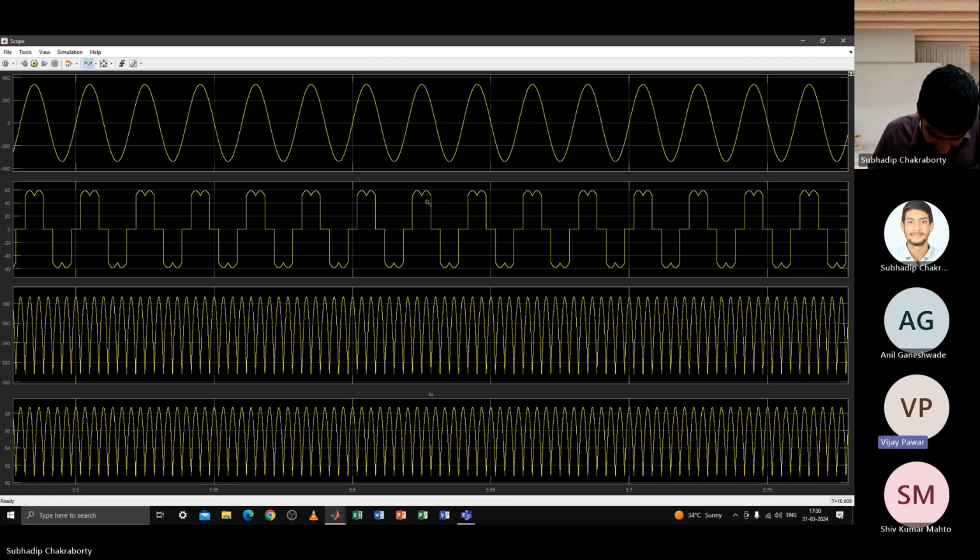Please understand, there are harmonics. So if you want to provide harmonic compensation, which you will do for these kinds of loads, such that your supply side doesn't have any harmonic, then the current rating of the filter will not be 0, because your filter will provide a low impedance path to the harmonic components. Then how can it be 0? Only the reactive component of your current is 0. That's why you don't need reactive power compensation. That's what I am telling. It does not necessarily mean that the filter will not handle any current. The filter will handle the harmonic component of the current.